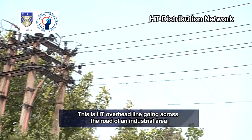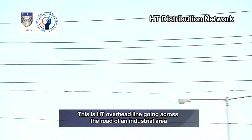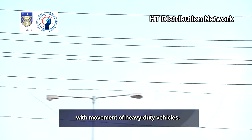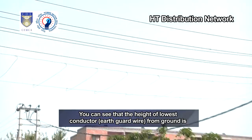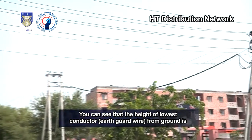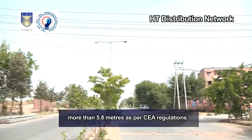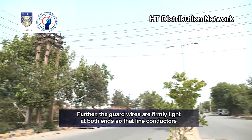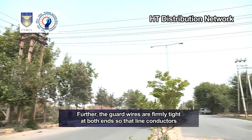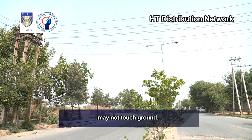This is an HT overhead line going across the road of an industrial area with movement of heavy-duty vehicles. You can see that the height of the lowest conductor earth guard wire from the ground is more than 5.5 meters as per CEA regulations. Further, the guard wires are firmly tight at both ends so that line conductors may not touch the ground.